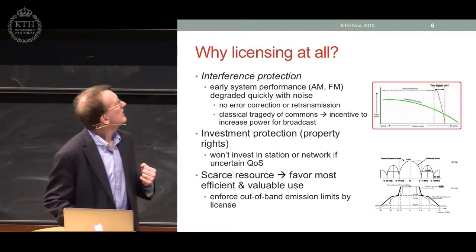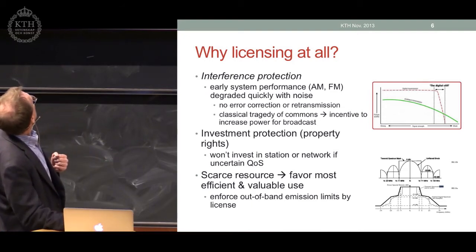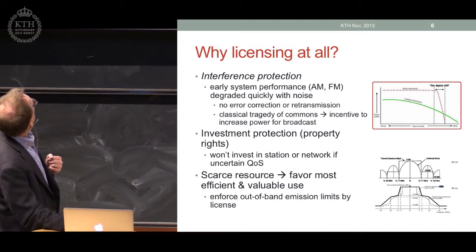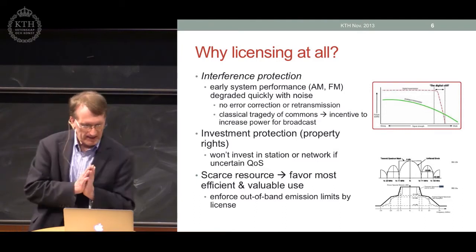Particularly if you look at the kind of system performance that you get here, you see that in a traditional analog system, performance goes down and down and down as you get less signal strength or more interference. In modern digital systems, they're a bit more robust, but essentially, once you exceed their system design limit, they collapse. So basically you get no signal, no picture at all, as opposed to a noisy picture.